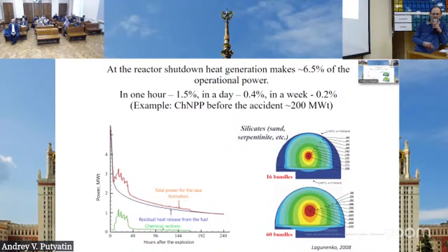after the interruption of the reactor operation, you cover them with thermal insulation and the temperature rises very rapidly. Why is this? Is that because immediately after the stop, scram, or immediate stop of the reactor operation, the residual heat release is approximately 6% of the operational power.